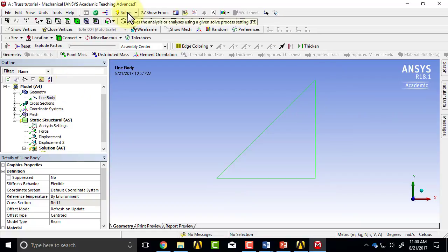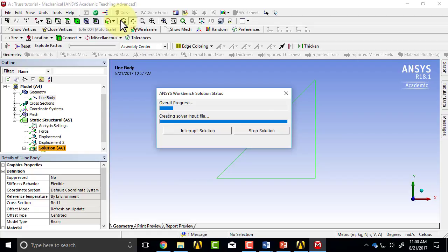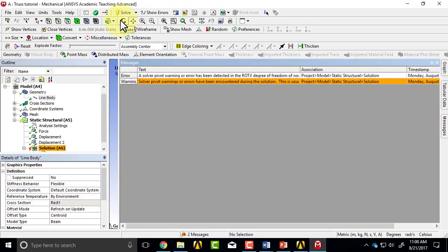So I'm going to click on solve, and if you're so inclined, you can say a prayer before that. So click on solve. In this case, the prayer didn't help. Sometimes I guess that happens. And by the way, this is a dreaded error, the solver pivot error, because it means that it's not able to invert the algebraic equations that are generated.